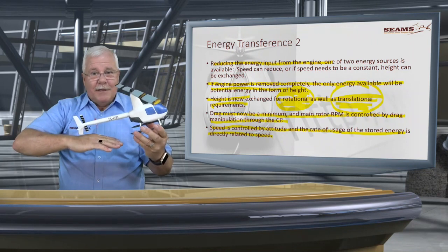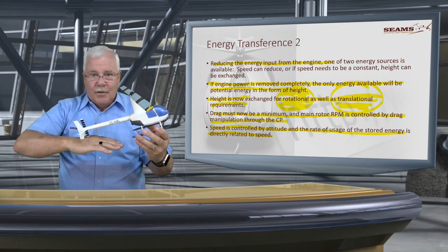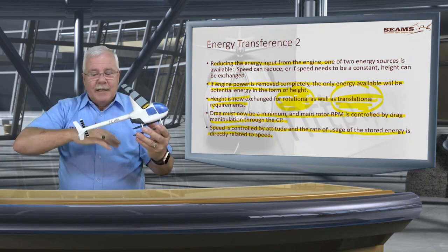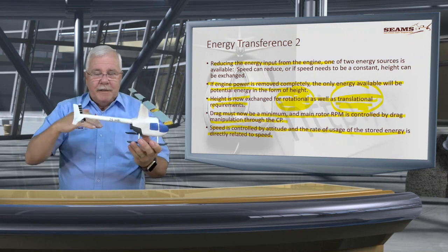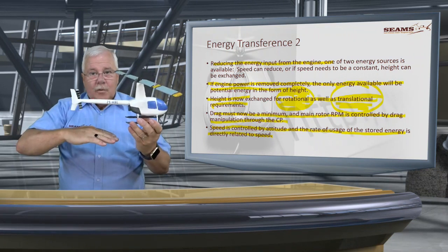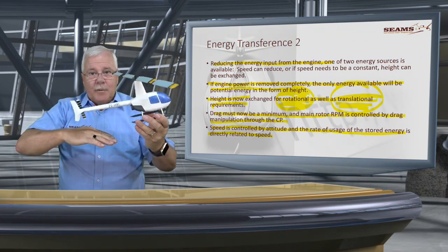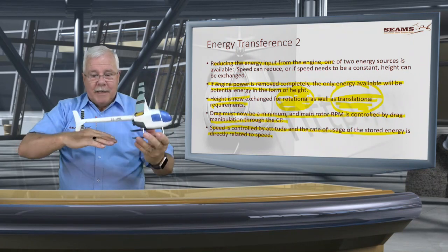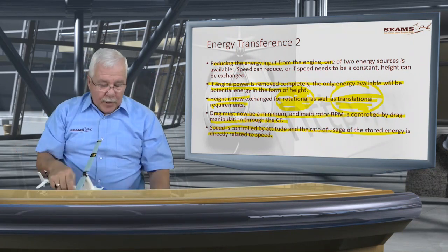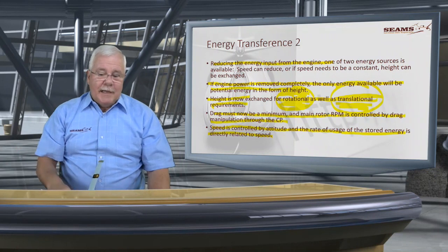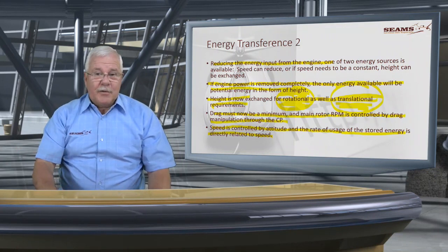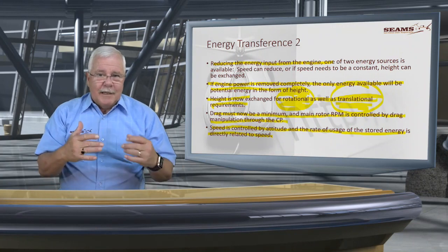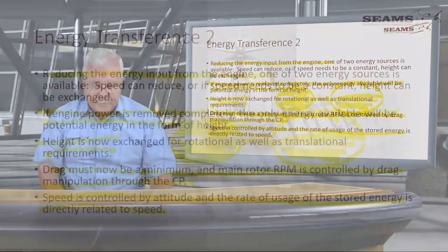There's no other thing. Not good, because after that it's going to cut off the tail and do funny things. So you will always want to be able to go to a height where you can maximize the flare, and then you can break this forward speed and the rate of descent into something that the body can absorb.